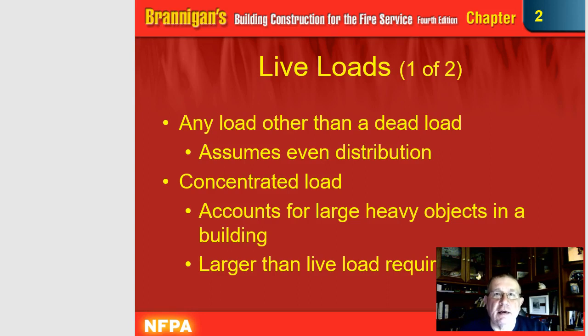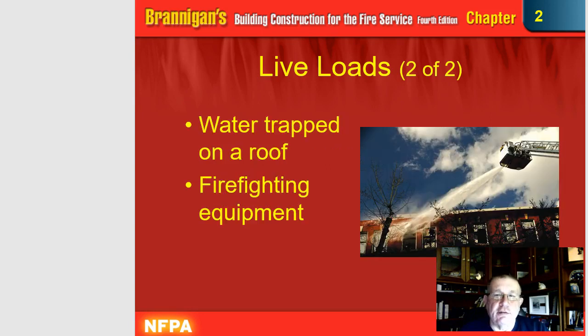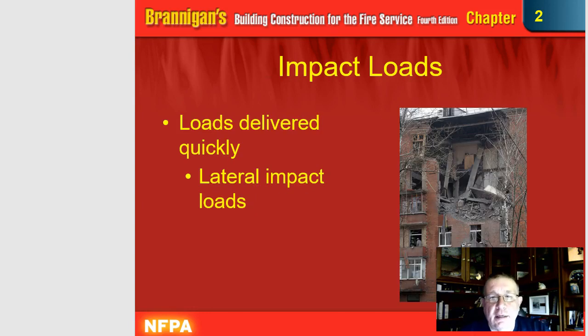And what do we mean by a live load? How about floors in a hospital when they're moving gurneys back and forth? Those are live loads in motion. The other thing is, what about live loads in firefighting? We got water trapped on the roof, fire equipment on the scene. It's all part of those important things that go on. An impact load. We see this once in a while, cars into the building. That's an impact load. You have lateral impact loads, where you might have one part of a building be hit, and also at the same time the building next to it suffers an impact because of debris going back and forth.